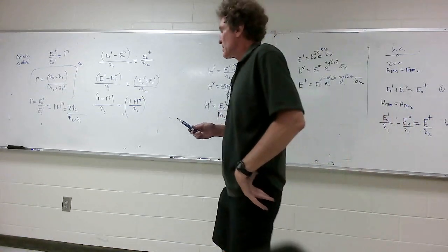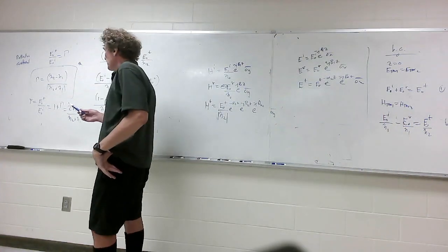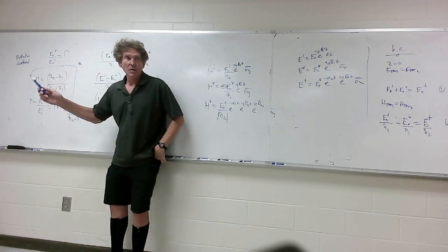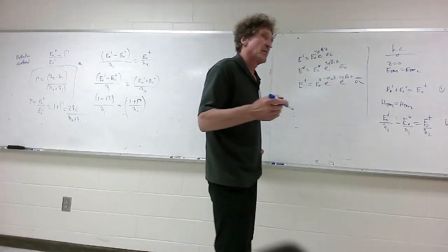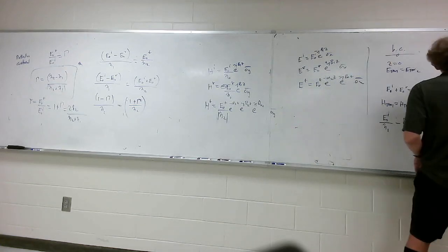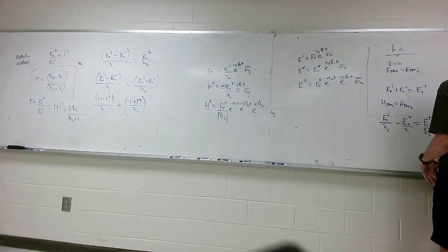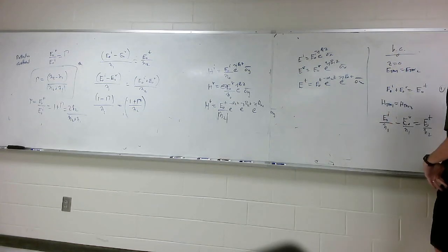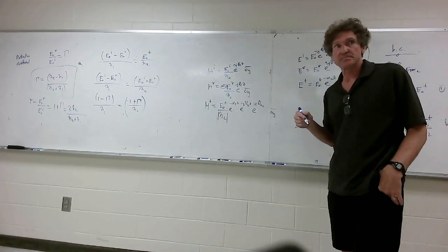When I look at this reflection coefficient here, what is the reflection coefficient if we say eta 1 is 120 pi and eta 2 is 0, a very good conductor? What's the reflection coefficient? Just look. That would be a short circuit basically.